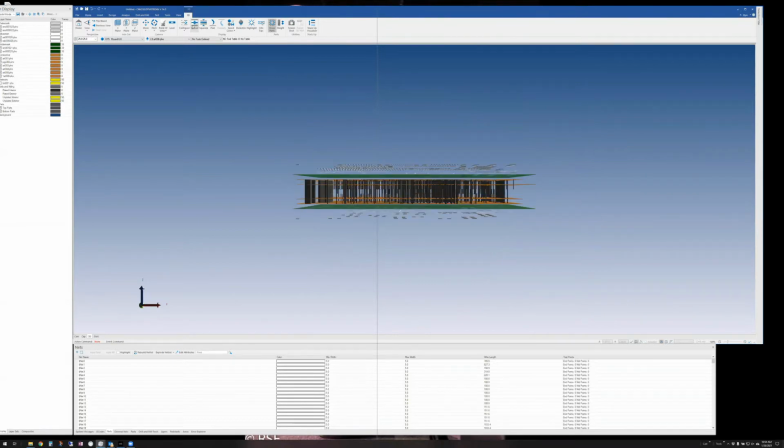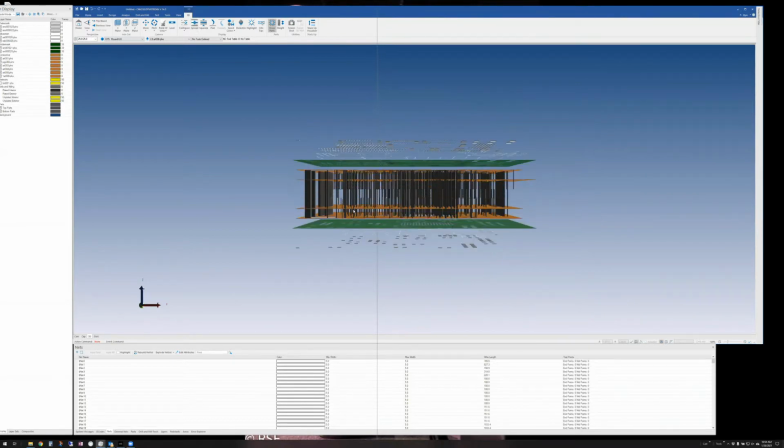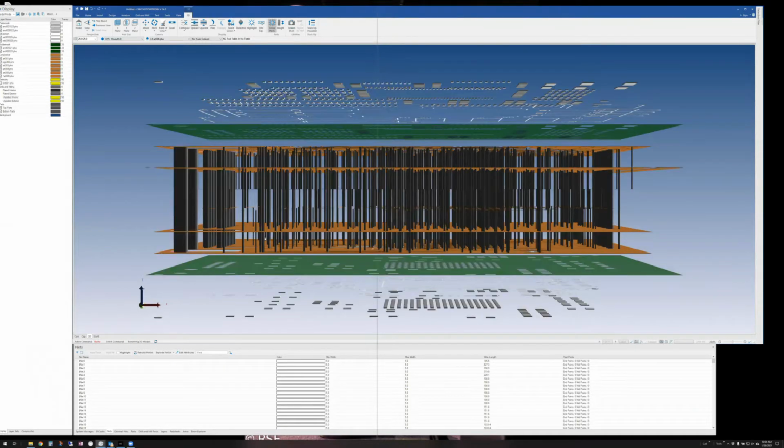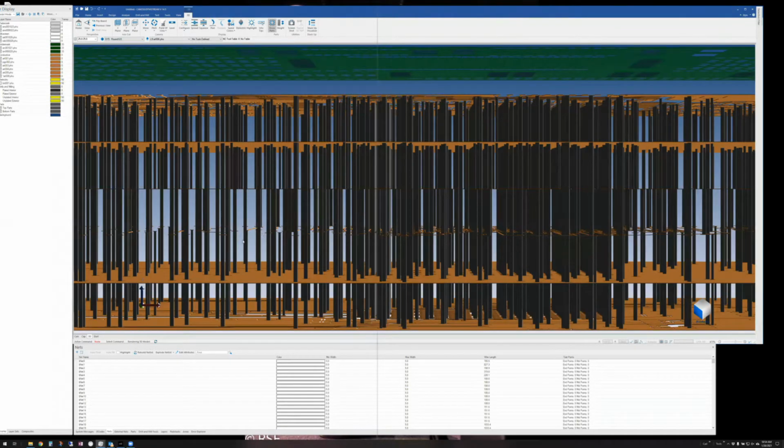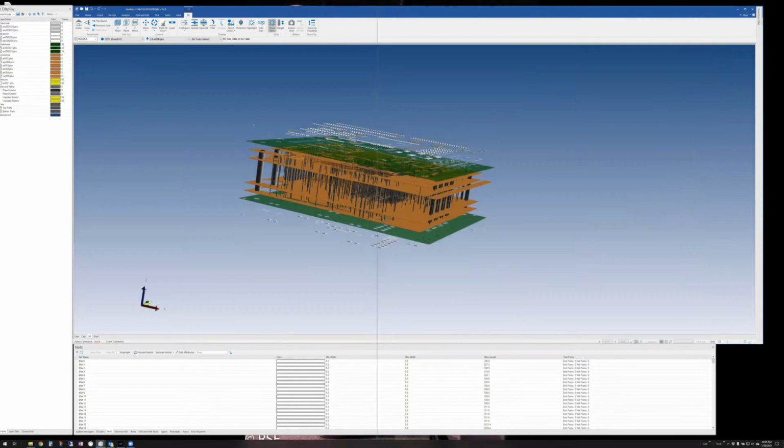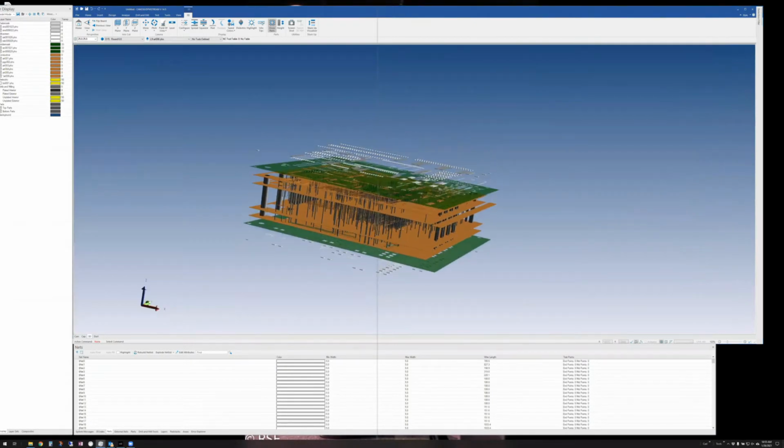And this is another way you could follow traces too, is that now if I zoom in, you can even see some of those partial drills show up, and they're not going through all the layers. Okay. So 3D does work with even Gerber and NC, and that's available in all of our products.